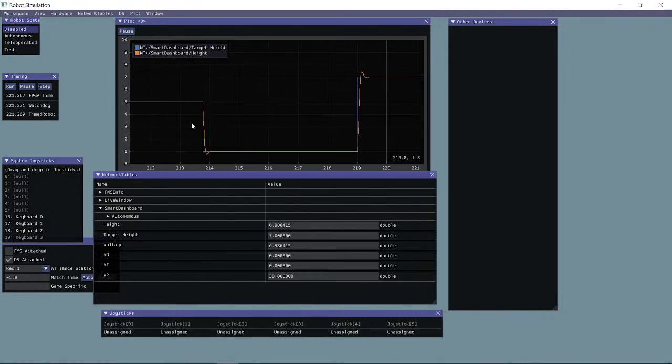Yeah. So from here, wait, can I pause this? Oh yeah. So from here to here, it was the same p-value, but that little oscillation jump was made smaller because my KD term was subtracting off because it was coming in really fast. So yeah, if I keep going with this, keep increasing KI because we still don't want even this little oscillation, we probably don't want that.